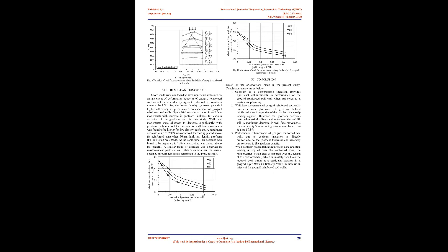A gradual vertical load was applied at a constant strain rate of 5 mm/min till the maximum settlement of 30 mm was reached or the maximum load of 35 kN was reached, whichever occurred earlier. Images were taken at a constant time interval with the help of a digital camera, Canon make, 9 megapixel, enhanced shutter speed. Images taken were stored in a connected computer located a few meters away from the test setup.